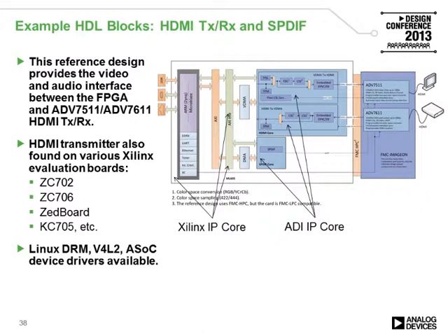Functional blocks within this HDL IP core are a color space converter, converting RGB 888 into YCbCr 4:4:4, a color space subsampler, converting YCbCr 4:4:4 into YCbCr 4:2:2, and a framer that is adding the embedded syncs. For the audio interface, we implemented the generic single-bit SPDIF interface, allowing audio in both directions. This whole design utilizes a minimum number of FPGA I/Os.